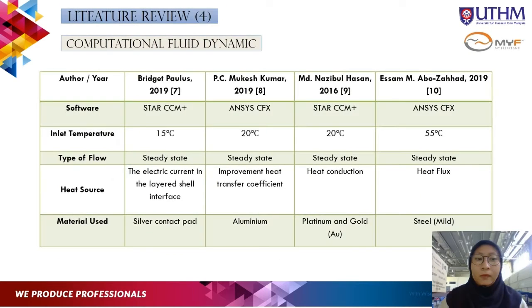Literature review number 4 is computational fluid dynamics. Based on the previous studies, they used different software, temperatures, heat sources, and materials. First, they used STAR-CCM+ with 15 degrees Celsius for the inlet temperature, the electric current in the layer shell interface for the heat source, and the silicon contact pad as the material.